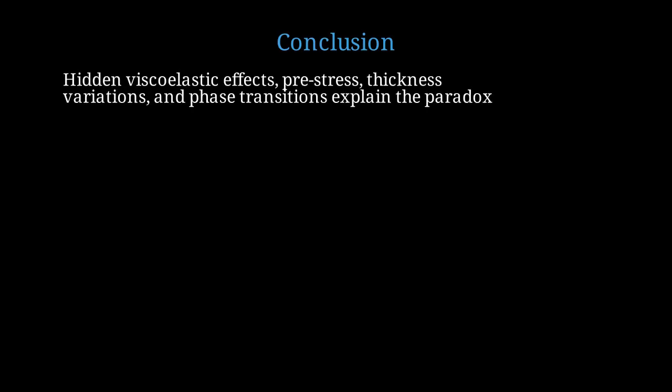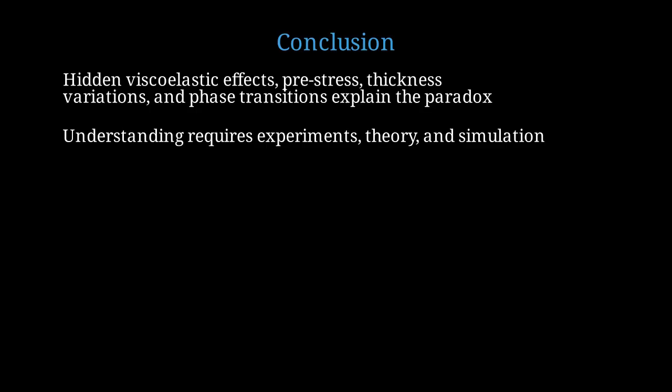We have explored the fascinating paradox of microcapsule buckling. While capsules behave like elastic shells, the onset of buckling often contradicts classical elastic theory. The resolution lies in hidden physics. Viscoelastic effects, pre-stress, thickness variations, and possible phase transitions all contribute to deviations from classical predictions. A complete understanding requires the combination of careful experiments, rigorous theory, and detailed numerical simulations.